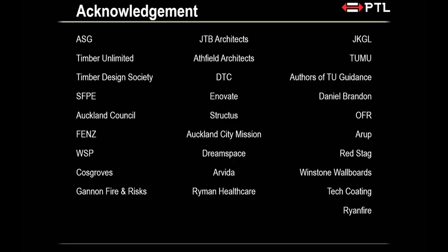What's your take on gaps, like 2 mil or 5 mil? Do you worry about that? I would. I think Eurocode sort of 2 mil, and then other people sometimes use 5, some people use I think less. I mean, for us, it's really anything more than 2, you should survey. Do something with that.